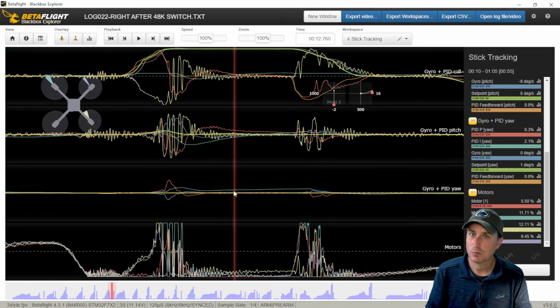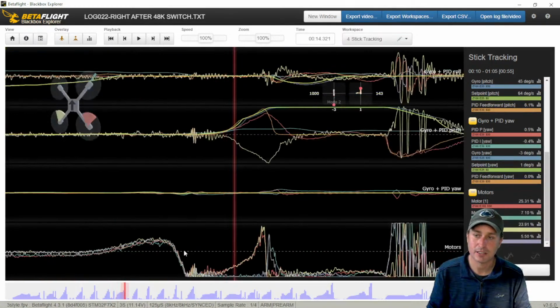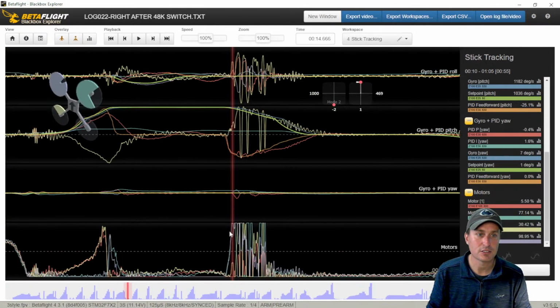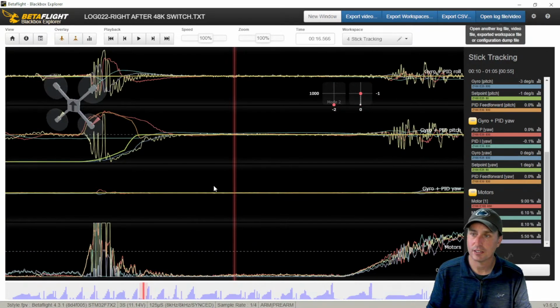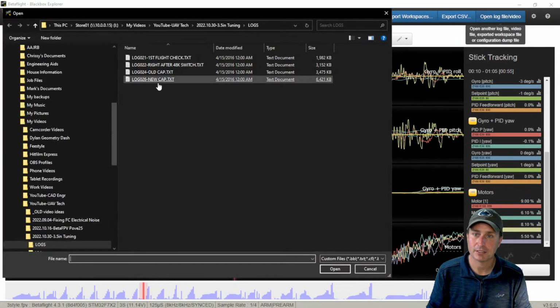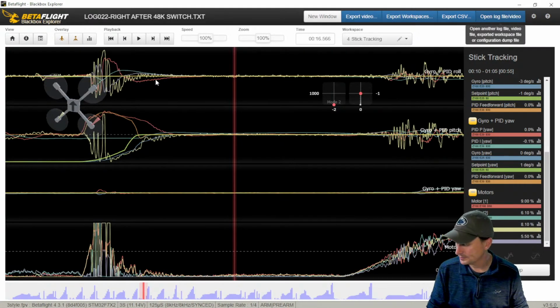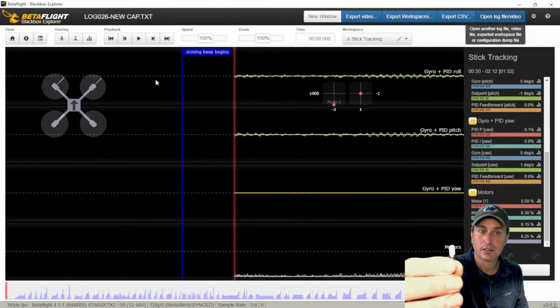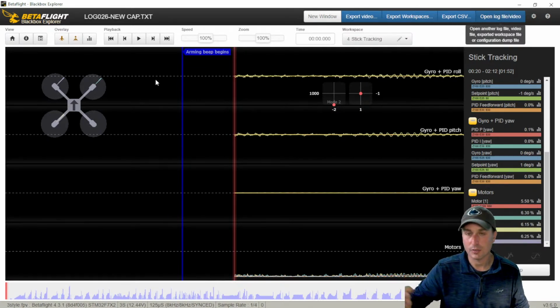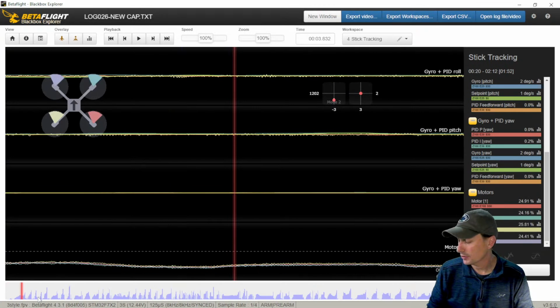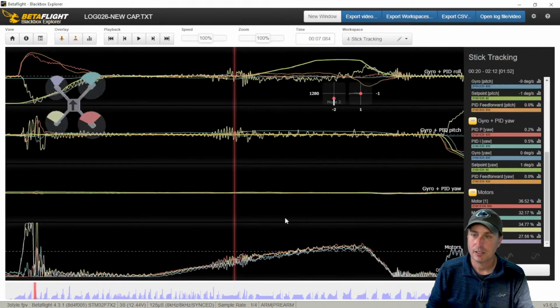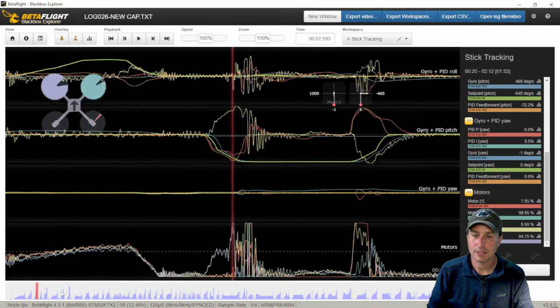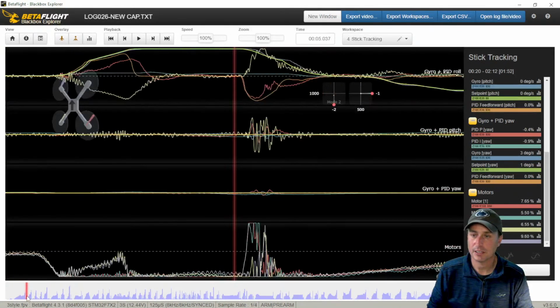And in flight, without looking at the log, you can't really notice this. So it was fine for tuning, but you can still see these issues here. I did try different things on it, like putting capacitors. I put a brand new capacitor on it. I put a tantalum capacitor on it, these little ones, on the 5-volt rail. That didn't really help anything. I don't think there is any exposed 3.3 volt rail, but I switched the capacitor out to a different capacitor, like a Panasonic one that I had.